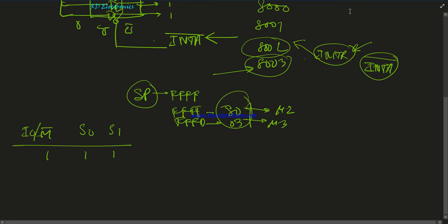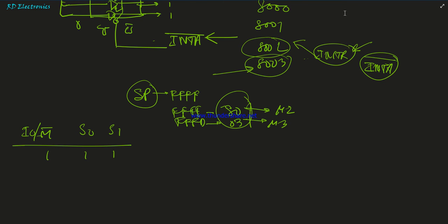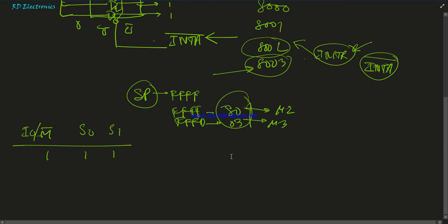It is a 1 byte call instruction of location 0028, and the machine cycles M2 and M3 are the memory write machine cycles that store the content of the program counter on the stack, and then a new instruction cycle begins. Now in the next instruction cycle the program counter is transferred. Our main sequence is starting from 8000. So when the interrupt occurs, it jumps to 0028 because this is the RST5 location. Now see the sequence. This is how the interrupt occurs in the 8085.